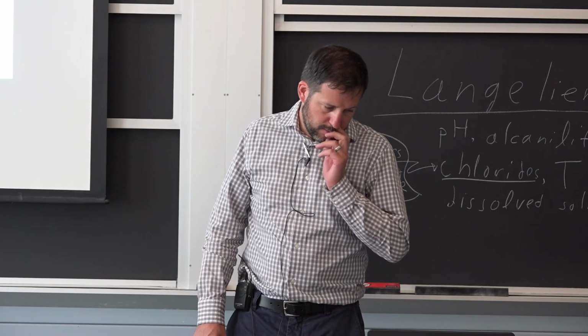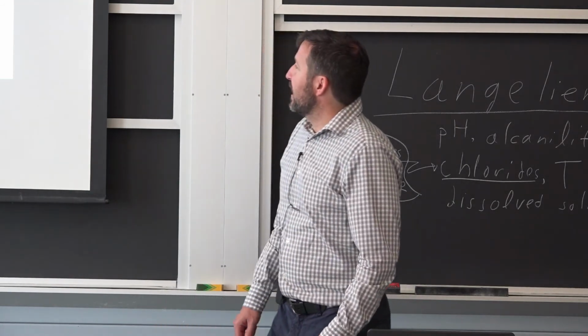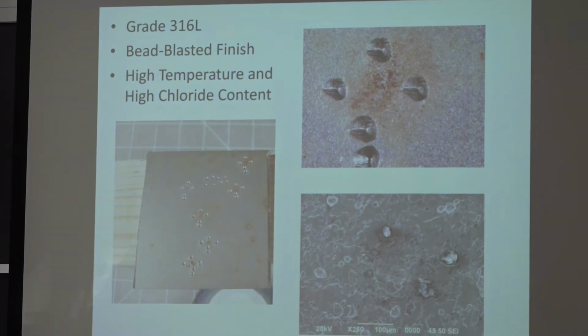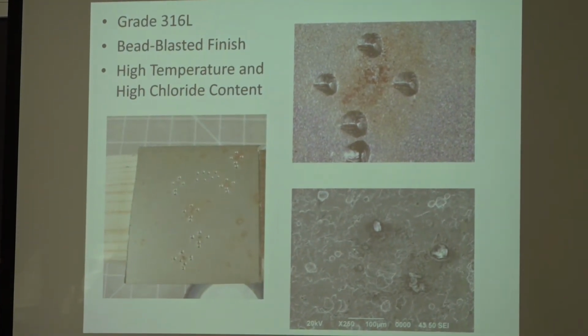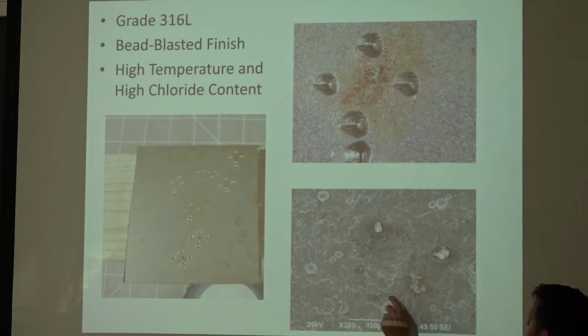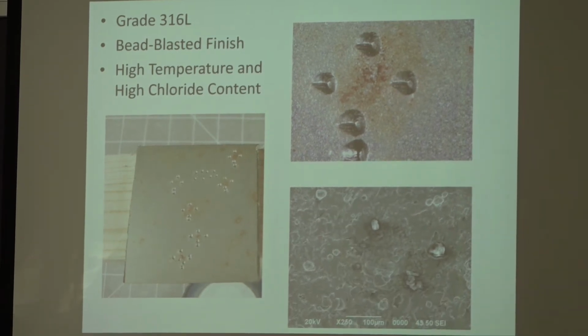Okay, what did we do? Did a little science here. So you can see all these marks were just to be sure we can tell exactly where we're looking. Because we decided to do microscopy in the area where it looks like the source of the rust was, which means you have to go and magnify quite a bit. So this is a small magnification here of the same area, and then zooming in a lot deeper here on the electron microscope, where you see our sand particles. So what I'm looking at here, here, and here are sand particles.